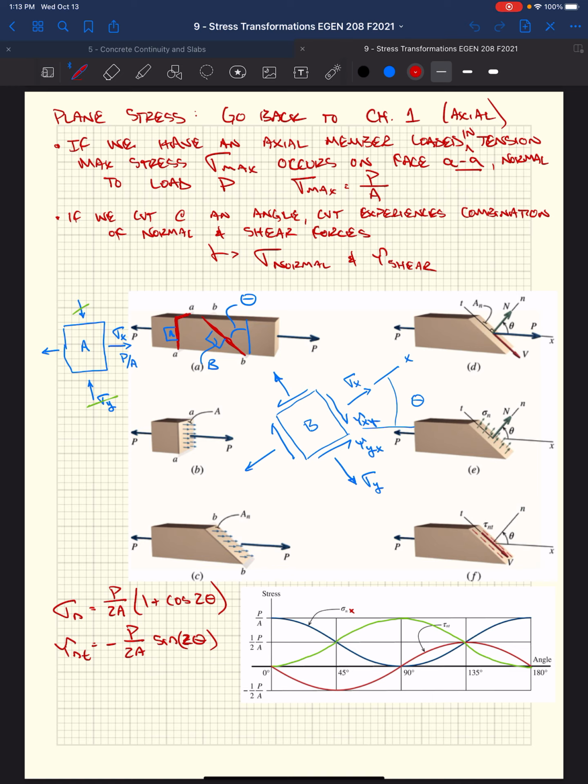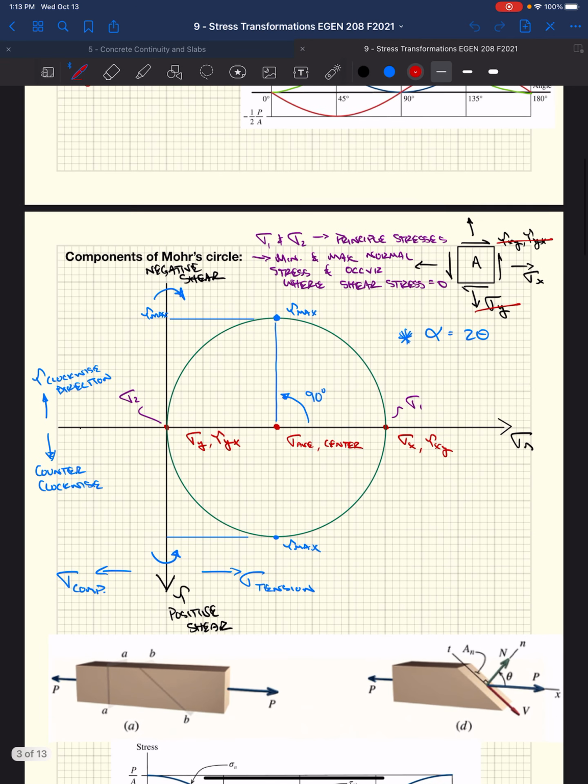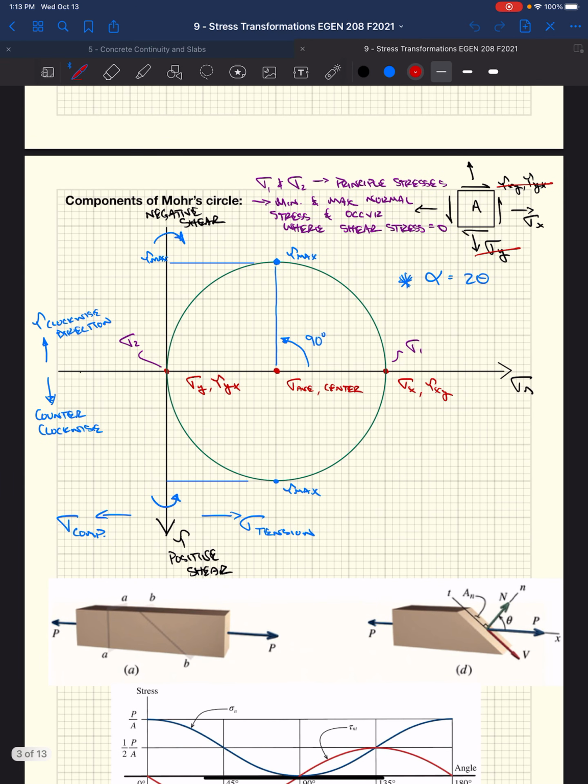And when we start combining loads and not only have axial loads, but say torsional loads, we added axial and torsion loads together on that example a little bit ago, right? And we figured out the stress state. And in those, we had shear stress and normal stress, okay? And so when we're faced with that, in order to develop the maximum stresses the element's going to see, both maybe for shear stress or for normal stresses, we use Mohr's circle, which I figured out was a German guy, okay?